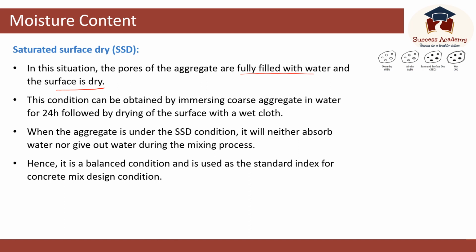This condition can be obtained by immersing coarse aggregates in water for 24 hours followed by drying of the surface with wet cloth. When aggregate is under surface saturated dry condition, it will neither absorb water nor give out water during the mixing process. Hence, it is a balanced condition and is used as the standard index for concrete mix design.